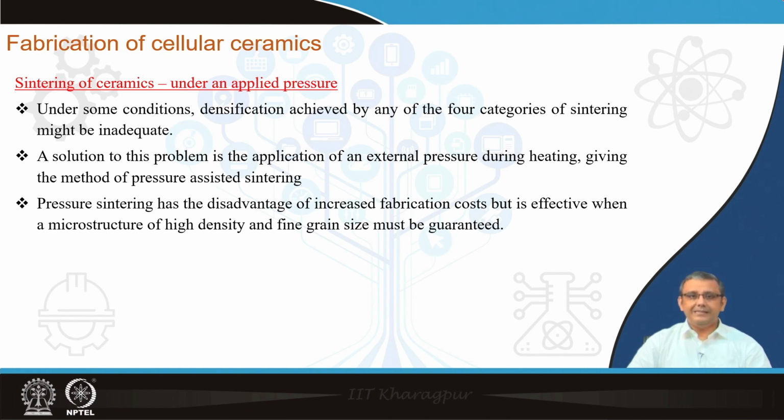At the same time, the disadvantage is that the process becomes much more expensive, because the equipment commonly used for pressure sintering is very extensive, since you typically require a combination of very high temperature and high pressure, and that requires very specific materials and also very specific atmospheres. Whereas, pressureless sintering can be performed in a typical muffle furnace, for example for an oxide ceramic, or in a normal tube furnace for carbides and nitrides, where a controlled atmosphere is required.